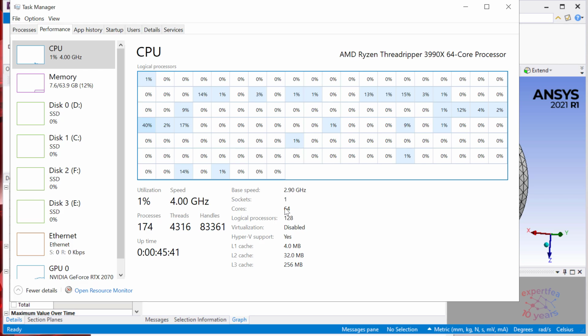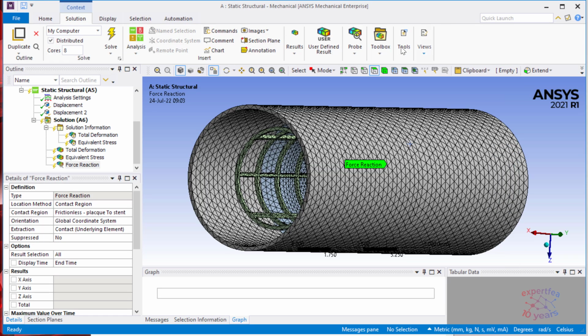If you don't do CFD, avoid the logical processors. When performing fluid dynamics you can use the logical processors. Just when performing structural and explicit, go for the physical cores.